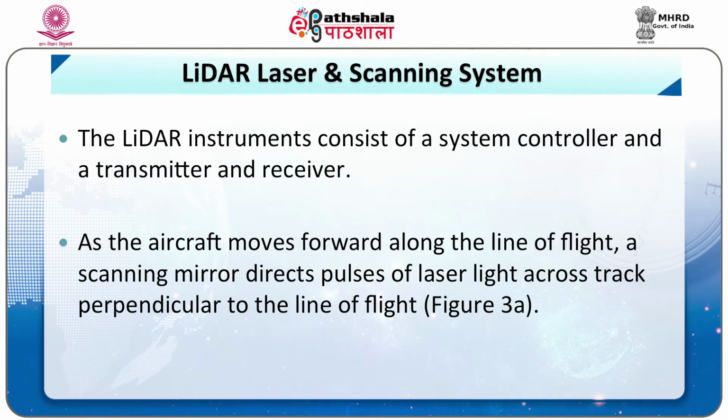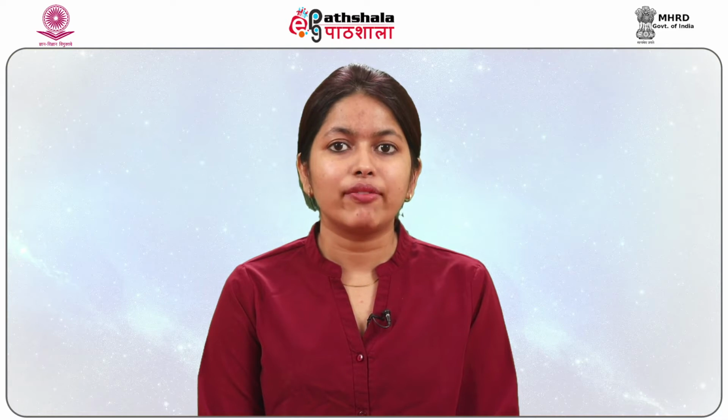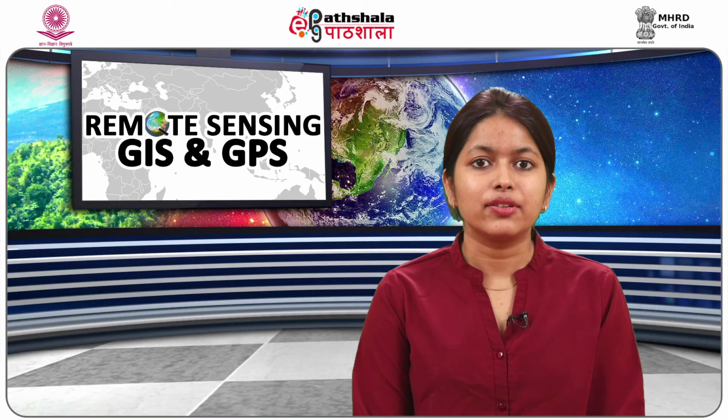The next is LIDAR laser and scanning system. The LIDAR instrument consists of a system controller, a transmitter and a receiver. As the aircraft moves along the line of flight, a scanning mirror pulses laser light across track, perpendicular to the line of flight, as shown in figure 3a. Most LIDAR used for topographic mapping uses eye-safe infrared laser light in the region from 1040 to 1060 nanometers.